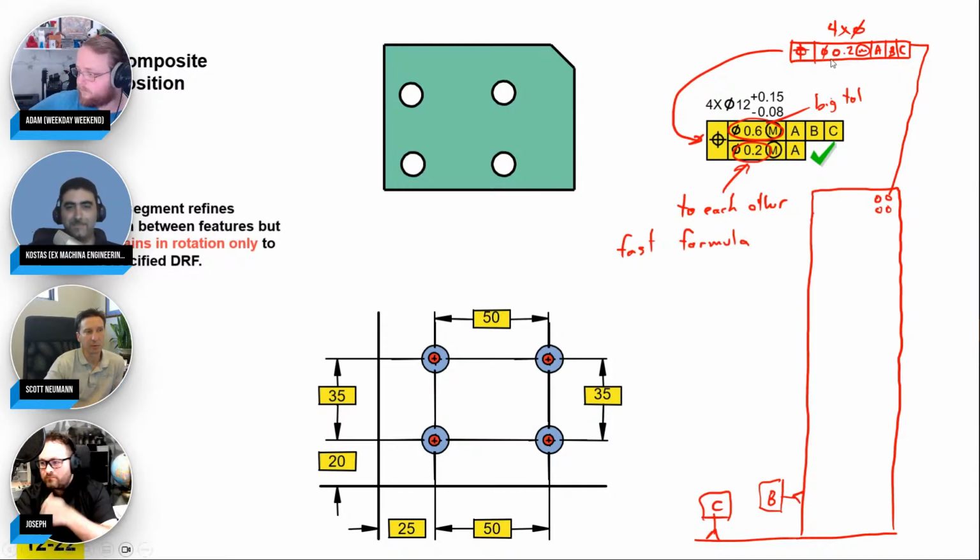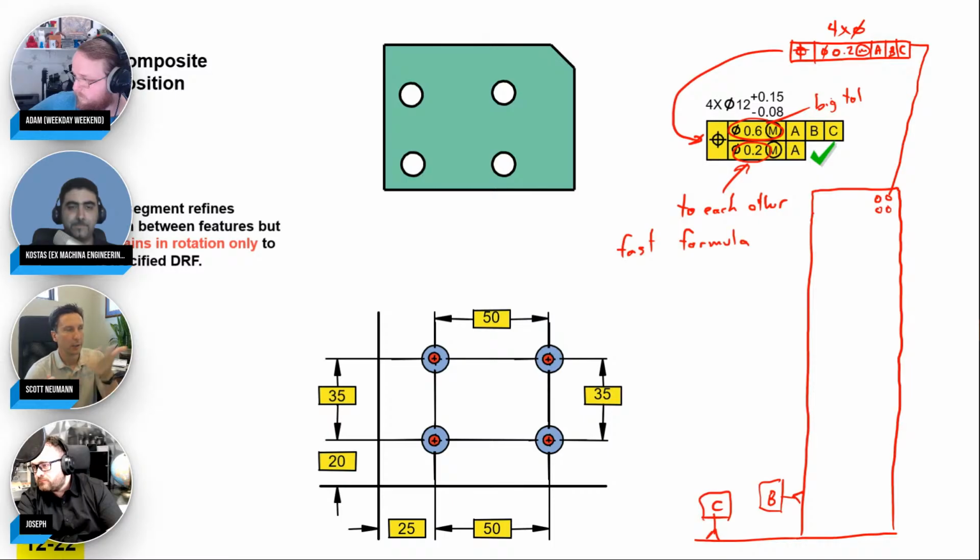And that's what I teach people. If manufacturing is good with the red one, oh yeah, good with that one, right? 0.2 relative to the datums, fixed fastener formula. But then you've got this one in your back pocket. It's usually for larger structures like big weldments or chassis or housings or something where you have a lot of components mounting on there, and they can kind of float and do their own thing as long as this better bolt up and that better bolt up and that better bolt up, but they can kind of shift off of your global reference frame a lot more.